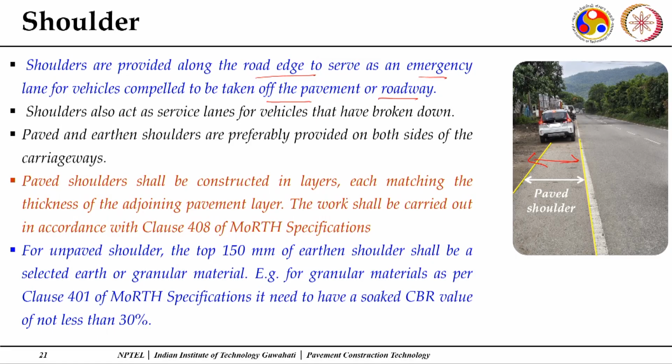Paved shoulders should be constructed in layers, each matching the thickness of the adjacent pavement layer. The work is to be carried out as per the clause. Now this particular clause states how the medians and shoulders are to be constructed. Clause 408 of the Ministry of Road Transport and Highways specifications, which we call the orange book, gives you details of how the different types of shoulders have to be constructed.